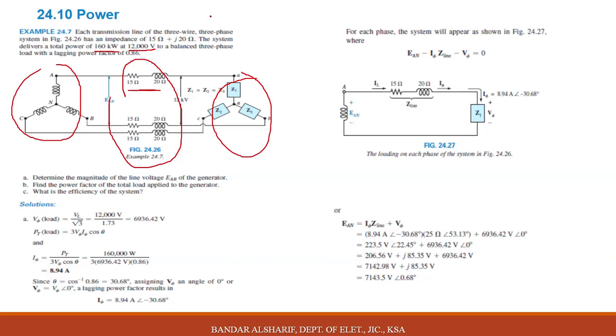In general, in all electrical books, if the voltage is mentioned in a three-phase system connection, for example motor, generator, transmission line, and the type is not specified, you will consider it as line voltage. Please be careful about this information. You will benefit from it later. In other courses, any voltage not mentioned or specified, you will consider it as line voltage. Okay, let us start.